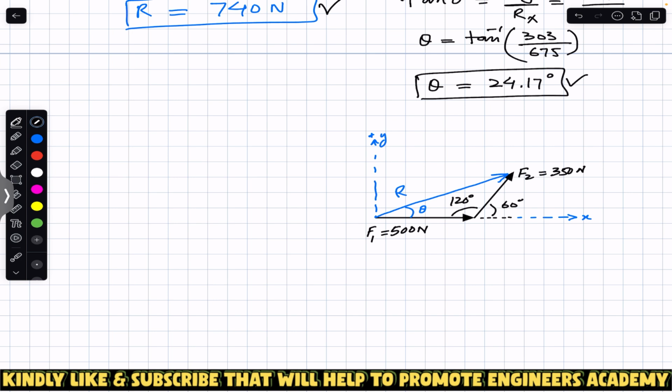We can use the law of cosines to find the resultant magnitude. So according to the law of cosines, r square is equal to F1 magnitude square plus F2 magnitude square minus 2 times F1 F2, and the angle which is in front of this resultant. So in order to apply the law of cosines, we must know the angle opposite to this resultant. So that angle is 120.